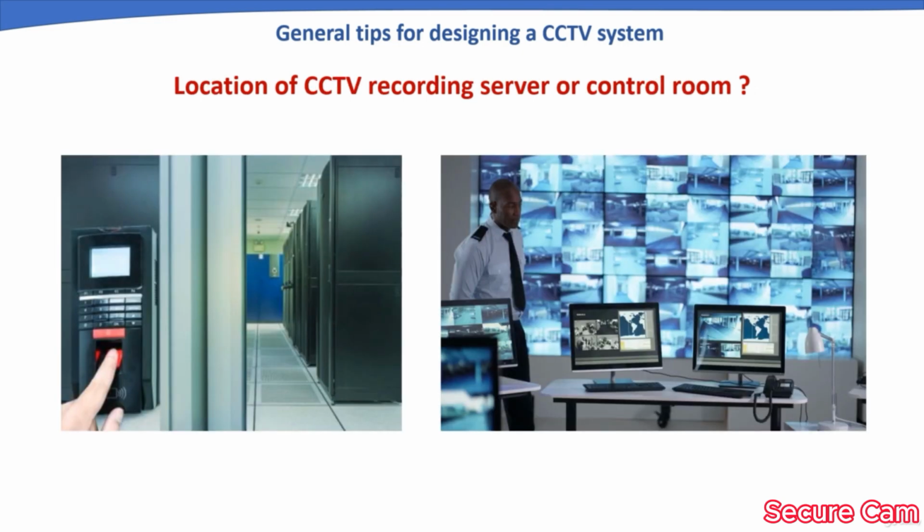Location of CCTV recording server or control room. As a CCTV system designer, one must have this information and make the customer aware that the NVR or recording storage server must always be kept in a secure place so that an intruder cannot easily tamper with the CCTV system. In case of large organizations or business areas, there may be a requirement for a CCTV control room where a dedicated CCTV operator monitors the entire premises via CCTV cameras and takes preventive action upon finding any security related issues.